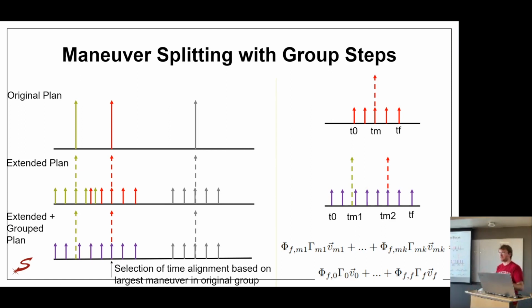I should note that VISORS has an embedded conic solver on board for its science mode control, which is what allows us to trivially accomplish this, because a linear program is a subset of a second order cone program, so it is trivially solvable by the solver we have on board, assuming that it works every time. If it doesn't work, we fall back to using the analytical solution with larger spread out maneuvers. But linear programs are efficiently solved, and they also give guarantees: if you can find a solution, it is the optimal solution.